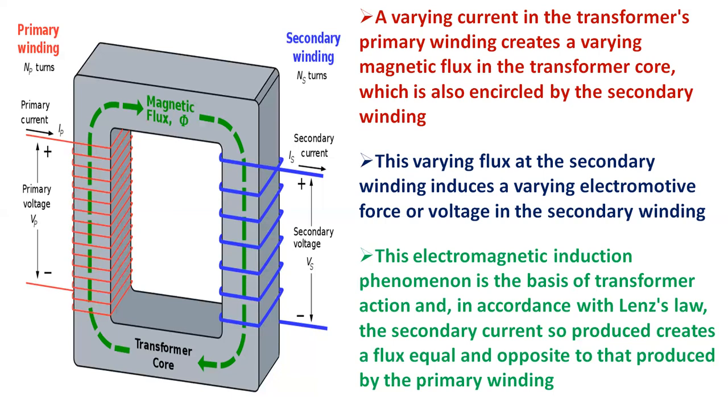According to Faraday's law, since the same magnetic flux passes through both the primary and the secondary windings in an ideal transformer, a voltage is induced in each winding proportional to its number of windings. The transformer winding voltage ratio is equal to the winding turns ratio. An ideal transformer is a reasonable approximation for a typical commercial transformer, with voltage ratio and winding turns ratio both being inversely proportional to the corresponding current ratio.